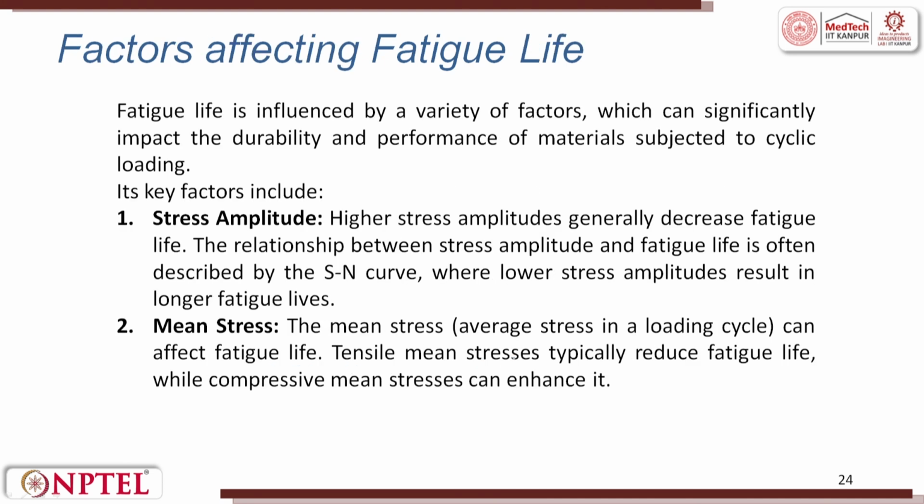The factors affecting fatigue life. The fatigue life is influenced by a variety of factors which can significantly impact its durability and performance when subjected to cyclic loading. One can be stress amplitude, the second one can be mean stress. Higher stress amplitudes generally decrease fatigue life. The relationship between the stress amplitude and the fatigue life is often described by an S-N curve, where lower stress amplitude results in a longer fatigue life. Keep this in mind. Lower stress amplitude leads to a longer fatigue life.